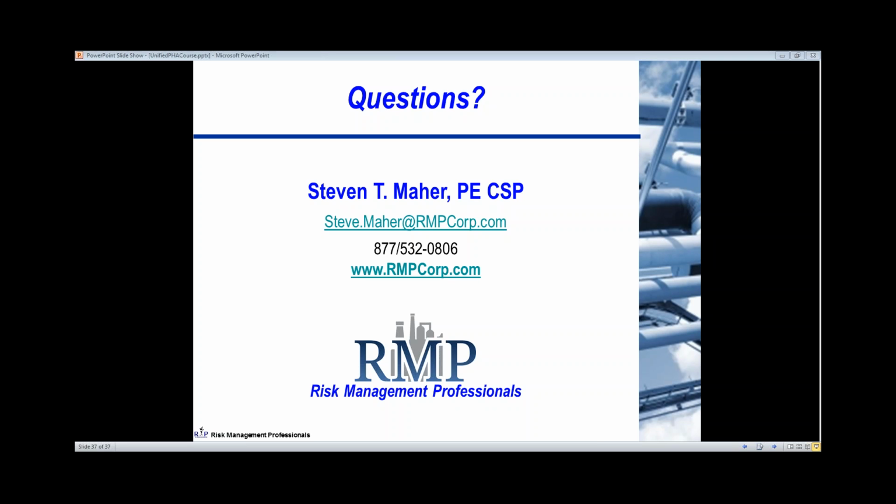And the same person who asked you regarding the PHA team members participating in a PHA, staying consistent over the years, commented saying, I find that a team often forgets to evaluate the near misses or incidents that have happened in the last 5 years since the last PHA, and a team does not evaluate the consequences and root causes of the failures in the PHA.